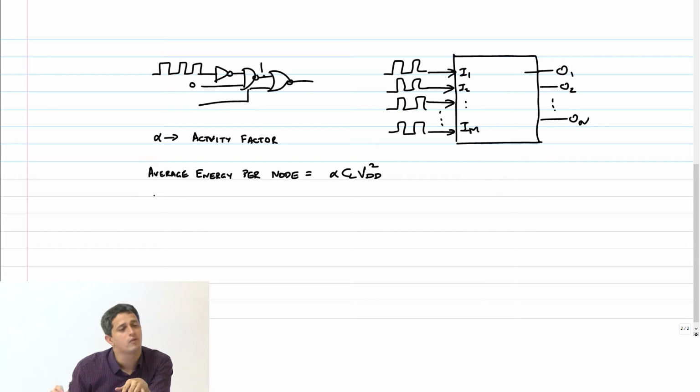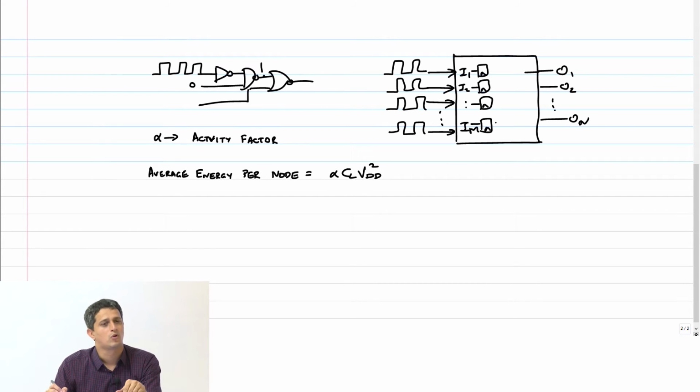So now how do we convert this to power? What will happen is, typically these inputs here, if you look at this circuit, will get buffered through flip-flops. So the input actually can change only every rising edge of the clock. Even if you apply it at a faster rate, it will not reflect in the change inside the circuit. So you can assume that all the inputs are synchronous and there is a central clock which is controlling the entire circuit, right?